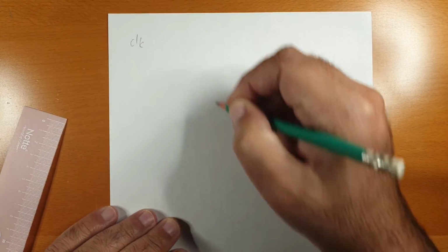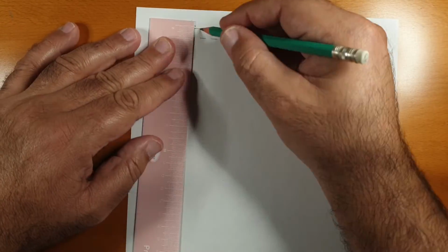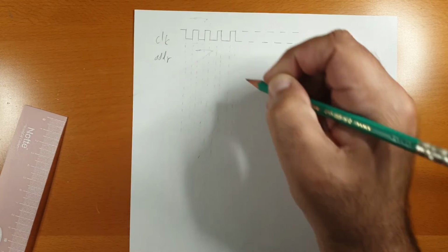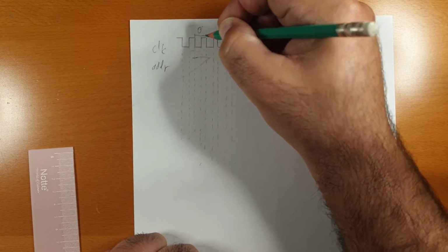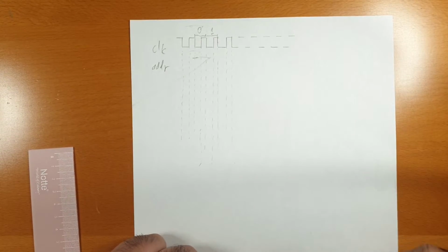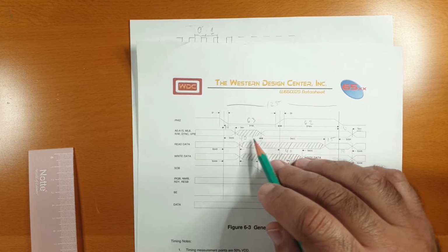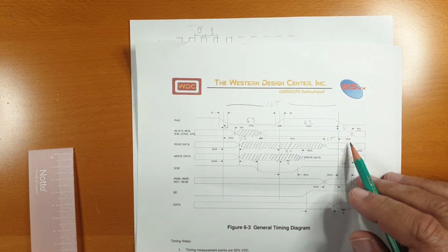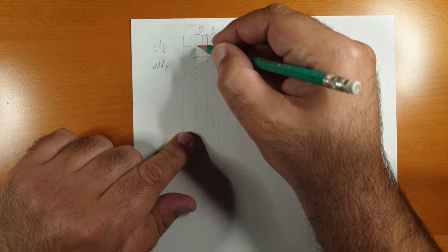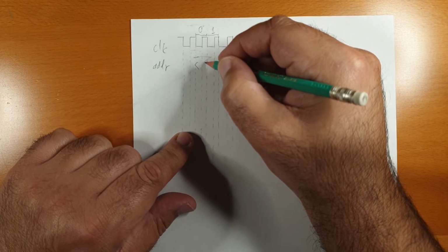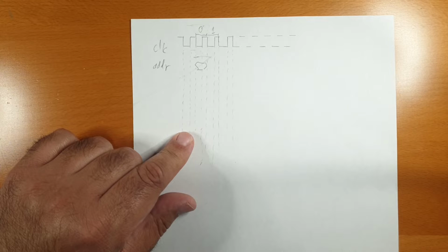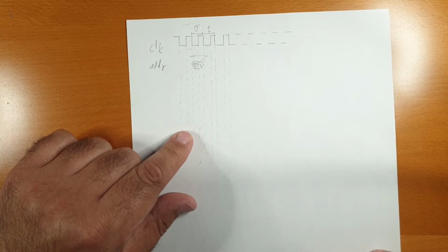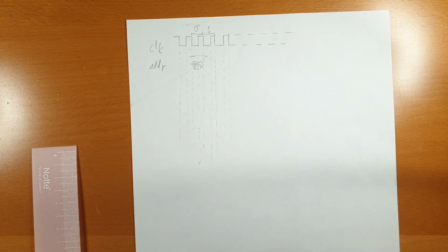So first we draw the clock, as usual. Next, let's draw the address bus. We'll call this cycle 0 of the command, and we'll call this cycle 1 of the command. Ignoring the hold time and the invalid time for the moment, the address bus needs to update between the falling edge and the falling edge of the clock. So between here and here, the address will contain where the first opcode resides. Let's assume it's address 400. And of course, since we're reading the opcode LDA, the data needs to be A9.